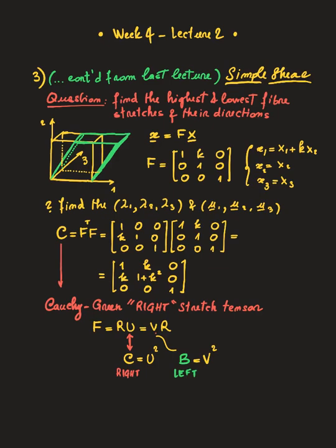Okay, so we will discuss more properly later on, but we have already discovered that the eigenvalues possess the properties of being the maximum and minimum stretching of the fiber, and for this reason we want to find them. We also want to find the unit vectors representing the directions in which these fibers have been deformed. On this I will go into more detail later on. So at this point, we essentially have to find the eigenvalues of C.